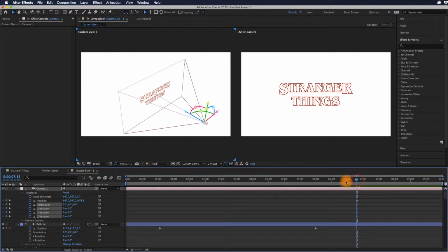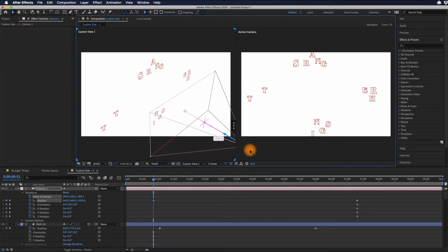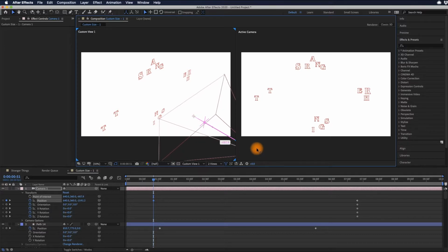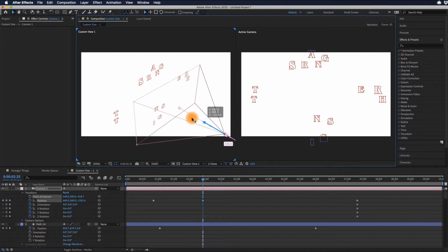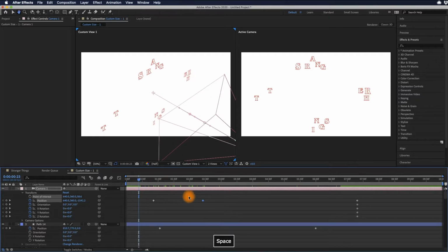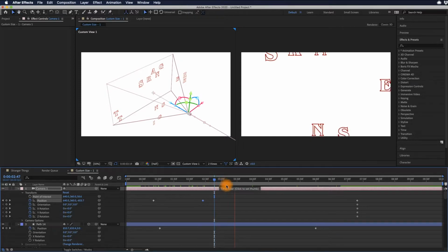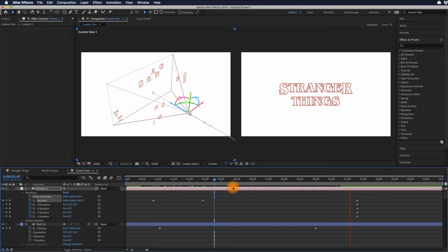The camera itself also has so many animations. But what we'll do is to create a camera with just the physical position change. Okay, so we key the first part, and also key all the rotations, and we create two pairs of keyframes to complete this animation. Okay, so the pink bar indicator is one camera. By changing with different camera settings, we can really see things in different views that we're going to introduce in the next part.